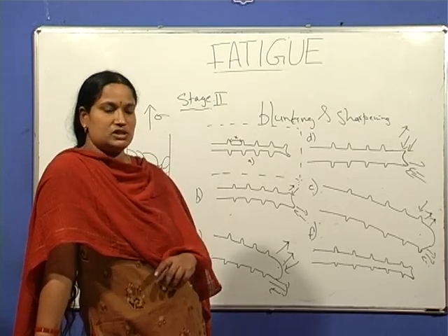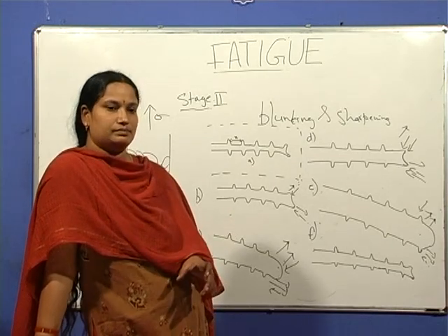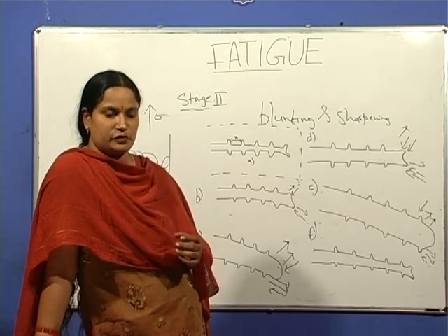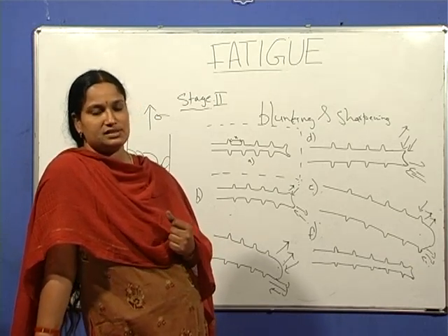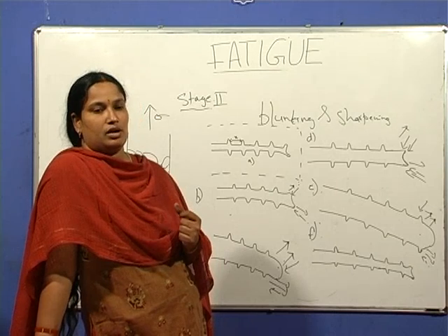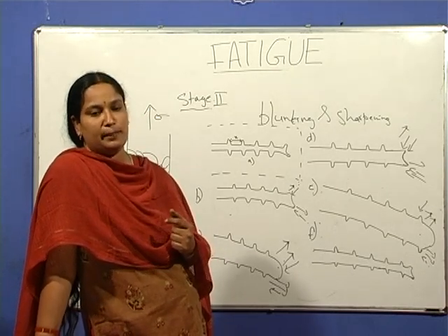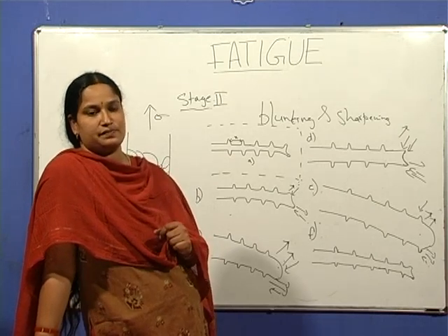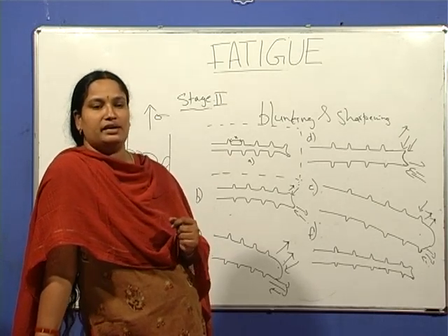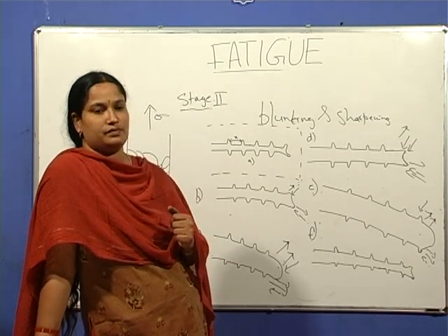These stress concentrators can be due to design-induced features like the keyways or the threads, or else they may be induced during the manufacturing process, like the surface roughness and the residual tensile stresses.